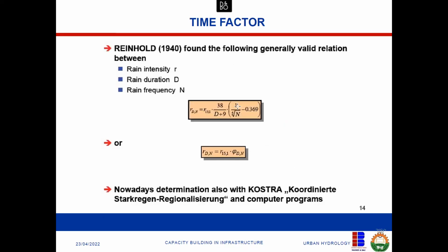Rural areas always use low values, because if rural areas are flooded, it's only the crops that are affected. But when you are designing for city centers, big cities, special cities, or where you have commercial activities, where rain would be disastrous, then you raise your safety factor.